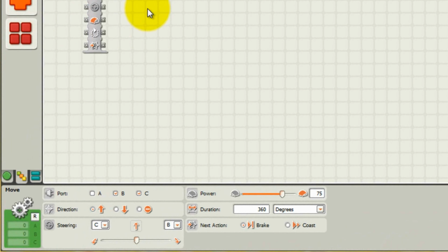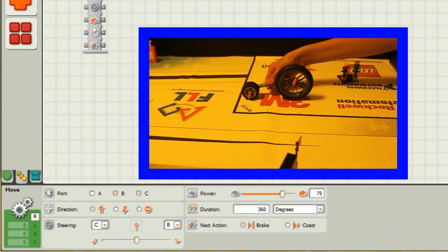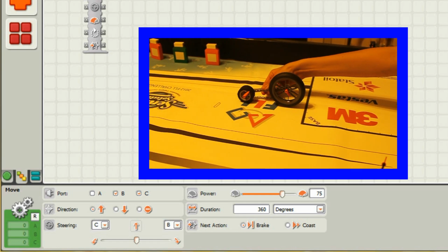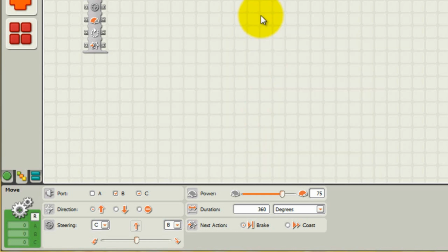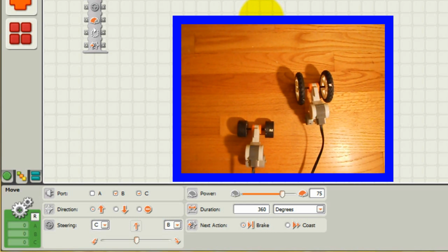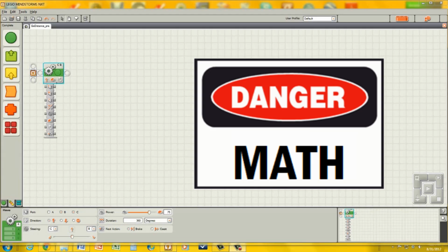The number of degrees to rotate the motor depends on the wheel radius of your robot's drive wheels. Think about it. If your robot has really big wheels, your robot will go further on one revolution of the wheel than if your robot has really small wheels. So our MyBlock must be told what the wheel radius is and must use this to calculate the number of degrees to rotate the robot's wheels.